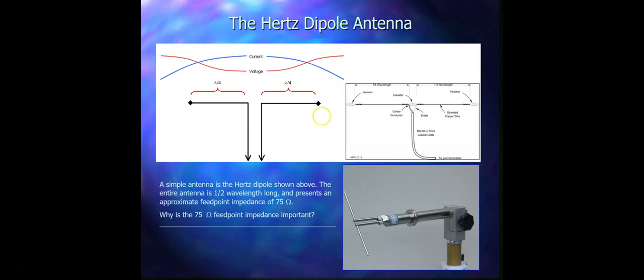Now if you use a coaxial cable, it will have around 75 ohm of impedance, which is actually excellent and provides an excellent match. When I say match, it means the radiation resistance of the antenna must be equal to the characteristic impedance. And when they both are equal, then the standing wave ratio is minimum, and maximum power will be achieved in the antenna.